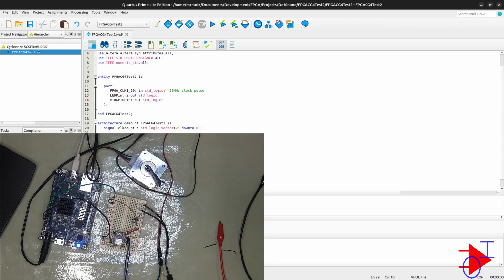We also want to pulse out at a certain point when the count reaches a certain value. So we say clock count, give me a pulse at about bit 15. Every time bit 15 goes high, we will forward that pulse.